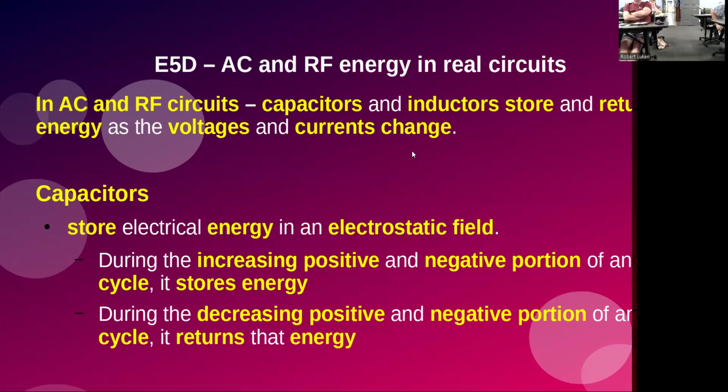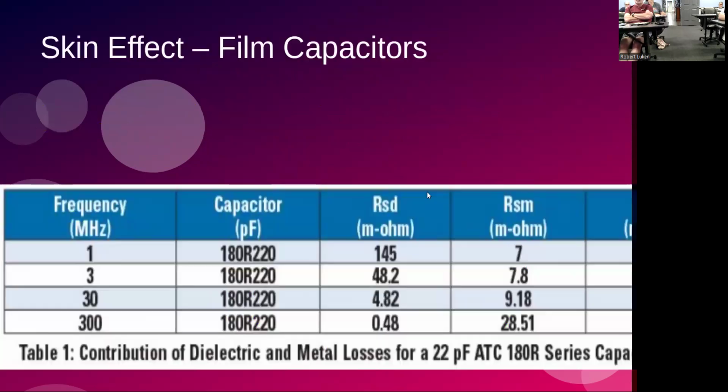Okay, so we talked about inductors and capacitors storing energy. And in a resonant circuit, they just transfer it back and forth between the two. Nothing really new there. There's a skin effect that also affects things like film capacitors. And as you increase frequency, it has more of an effect.